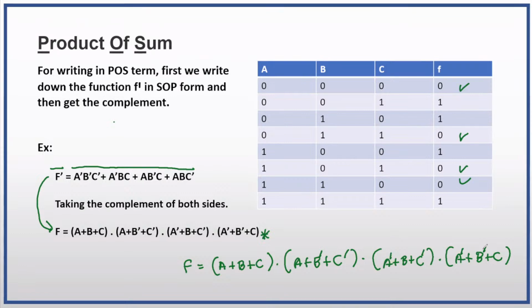So you can use it. For both methods you have to select zeros, and for the first method you can write the F prime and write it as the sum of products. And also in the second method, you can directly write this answer using the zeros. So this is how you can simplify the truth tables into functions. Got it. Okay.